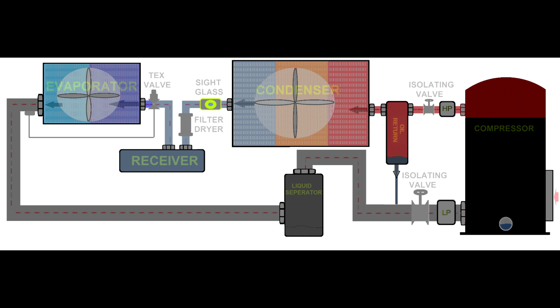So the refrigerant passes by the evaporator where it's boiling and absorbing heat, and then, superheated, goes into the suction line towards the liquid separator. Because sometimes we cannot control the superheat perfectly, we use a liquid separator. The liquid separator helps us to split the liquid from the vapors. We don't want liquid droplets to go into the compressor crankcase, otherwise we will destroy it.